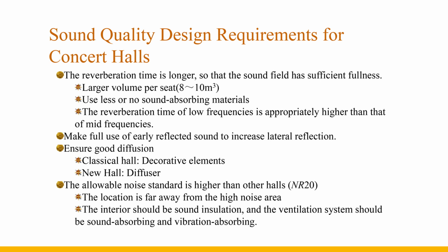If the reverberation time is shorter than 1.5 seconds, the music will be dry and thin. When the reverberation time is increased to 1.7 to 1.9 seconds, the music becomes active and powerful. No matter how long the reverb is, each note in the music will overshadow the next, and the rhythm of the music will be blurred. Therefore, the volume of each seat should be 8 to 10 cubic meters. At the same time, use little or no sound-absorbing material, and make the reverberation time of low frequency appropriately higher than that of mid-frequency to obtain a sense of warmth.